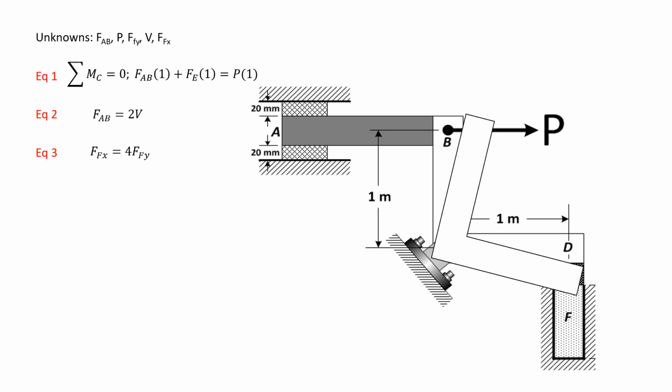How about the movement of point B horizontally? So you have two deforming bodies here. You have the rubber pads and the member AB. Both are subjected to forces. So what will happen? So the rubber pads will be feeling shear stress. And so they would incur shear deformation.